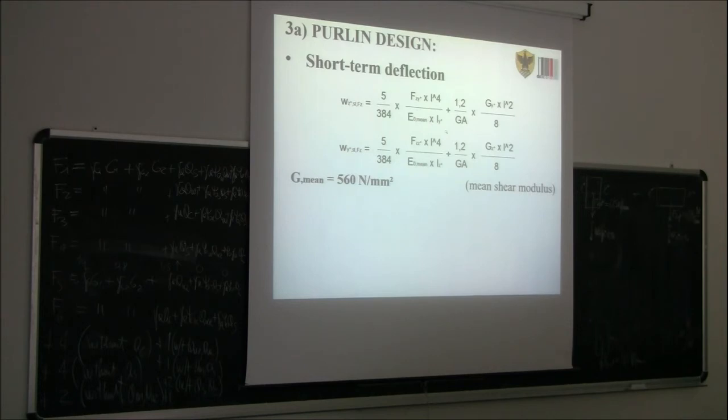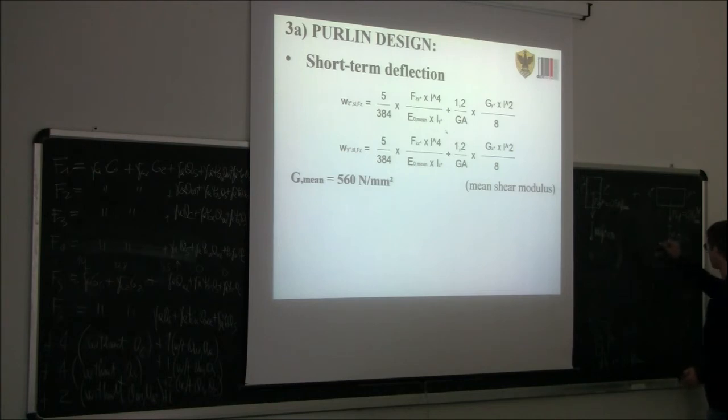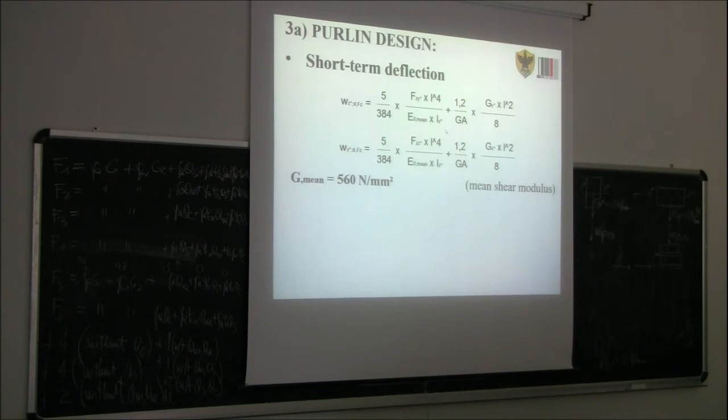But in some other cases, for example for a frame like this, you have a permanent load and there's no load in this direction. You have to do the combination with the wind, which is actually applying in this direction, with the seismic action, which is applying in this direction. So there you cannot simply sum and find the maximum value, because it's not possible, because they act in different planes. Okay? So this is more complex to consider, because this criteria of the maximum load condition is not so simple.